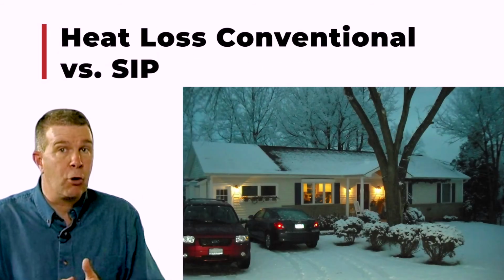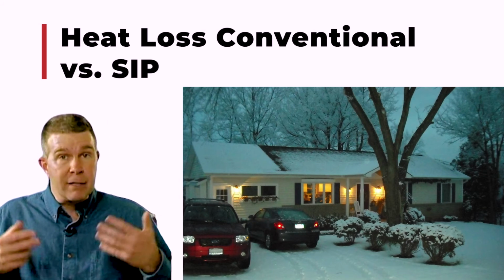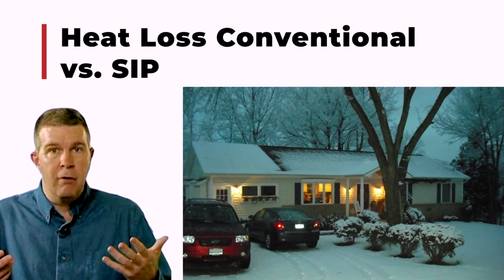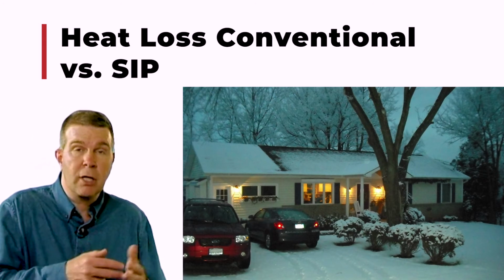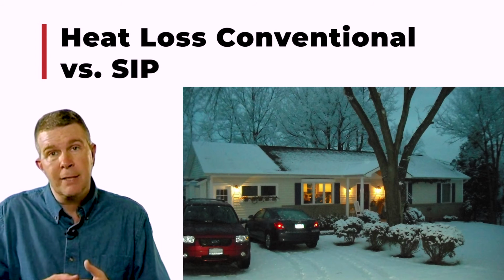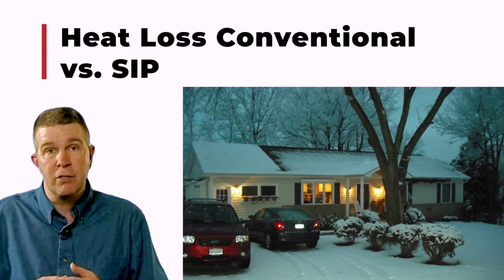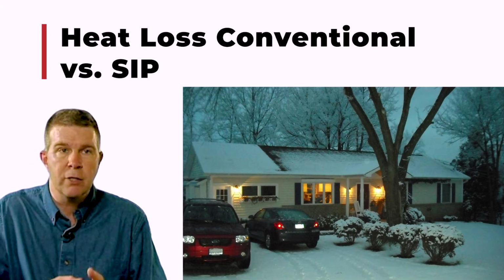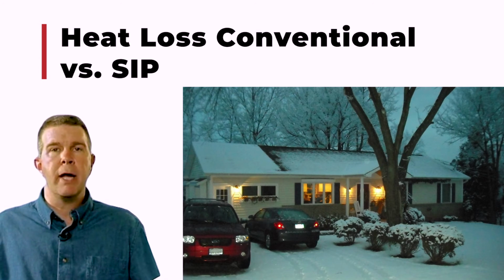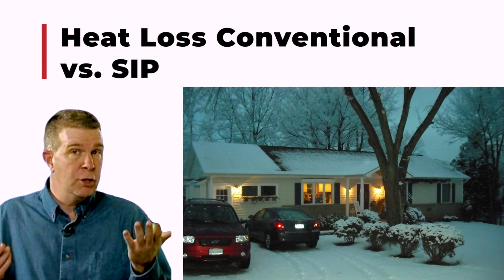This is a good example, a picture showing the difference between heat loss and the convective nature of heat inside of your building, in the difference between a conventionally framed attic and a SIP conditioned attic. In this picture, the SIPs are obviously on the left, and you can see the snow hasn't melted at all. And if you look over to the right, you can see where it's completely melted away. The difference in heat, with the inside temperatures being exactly the same, shows how these different systems perform.